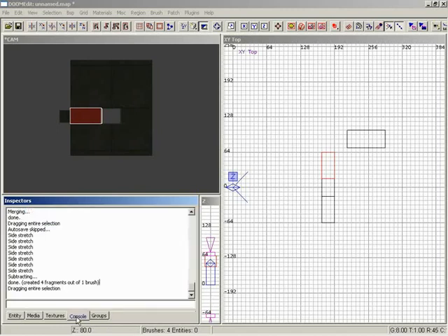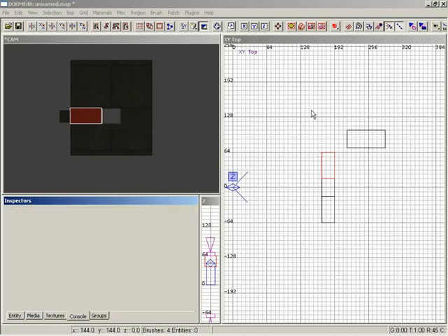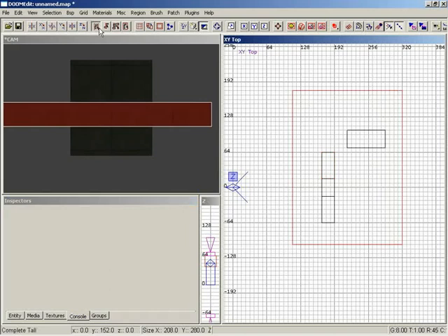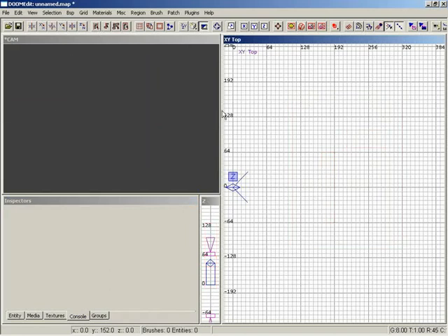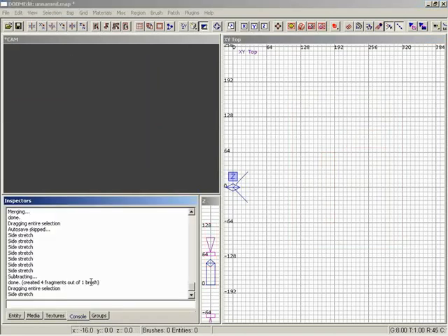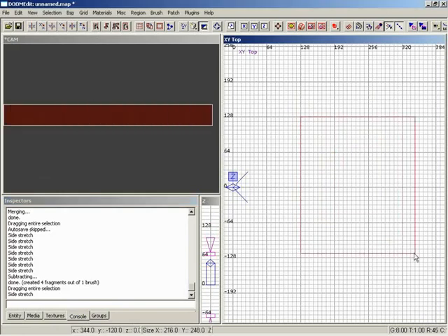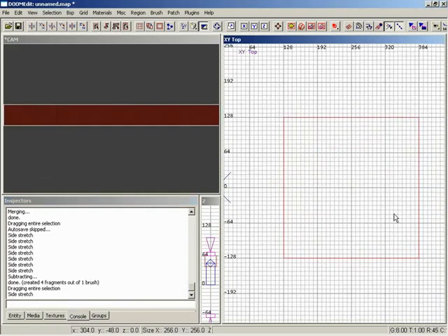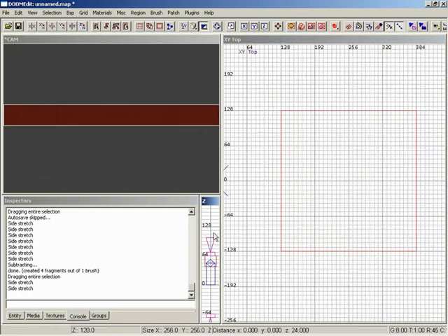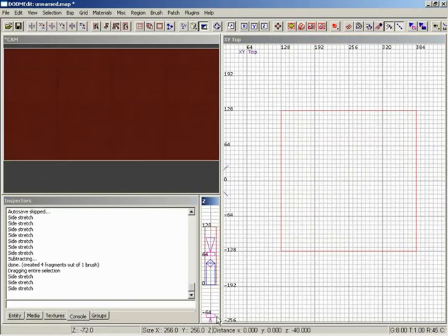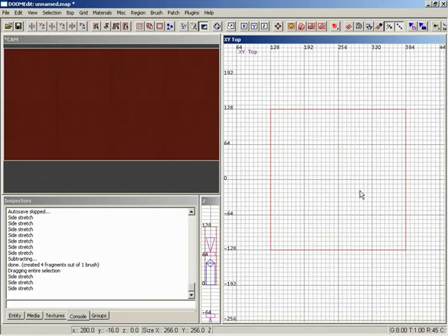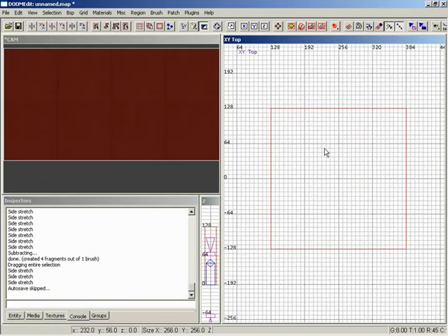First, let me get that back, and then I'll delete, or hitting escape in the wrong view. Let me select everything and take these out so we can start over with a clean room. Then console can come back. There we go. Now, let's draw out a new cube room, something about, like that should work. And then scale it up so that it's 128 units tall. So we have a room that we want to make into a playable area. And we want to do this with the subtract CSG operation now.